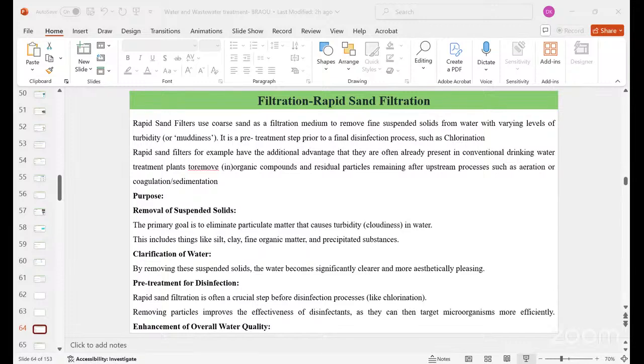So due to gravity only the water will be getting infiltrated through the sand filters, right? But during the backwashing it is reverse. And the chemical inertness, that is the media should be chemically inert in order to avoid leaching of contaminants into the water. So there should be inertness between the grains, such that the contaminants, once filtered through the filter bed, should not be leached into the water, otherwise there is no point of even doing the filtration, right?